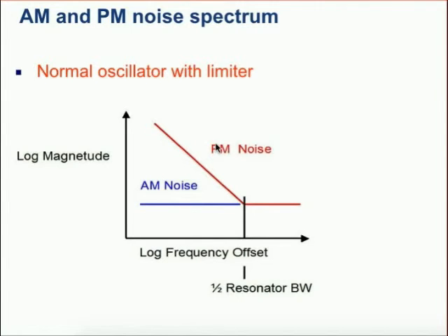To give a practical example of this, suppose we consider something like a pendulum, a mechanical oscillator, and this pendulum has a very high Q. Let's say it operates in a vacuum and it has magnetic bearings, so there's virtually no loss. So if it ticks once a second and it can run for a year, say, and only be 3 dBs down, it's got a very high Q and a very narrow bandwidth. The bandwidth is associated with that period of time it can run for.